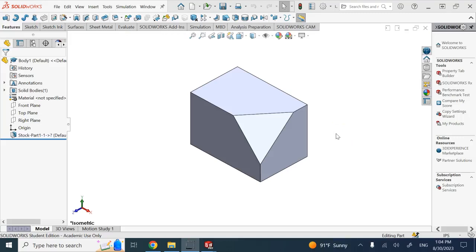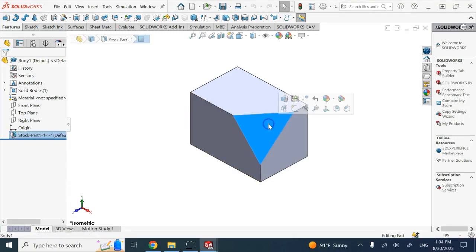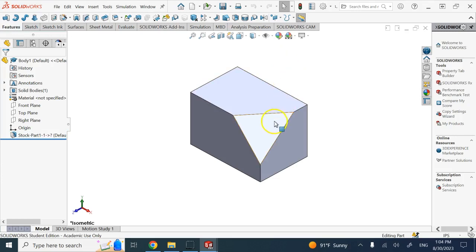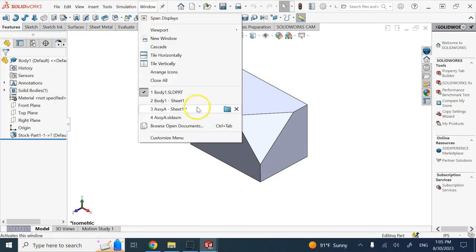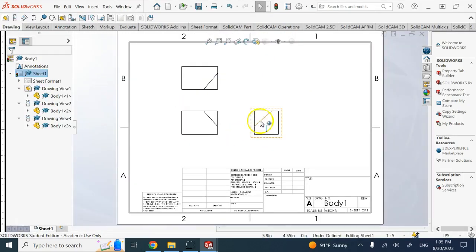Hello, everyone. One of the questions that you might have seen or came to your mind is, if I have what we call an oblique plane or plane type 3, the one that is not perpendicular and not parallel to any of the major three views, front, top, or right, and I want to see it in drafting, so basically do the front, top, and right view, then it would be something like this, right? In all three views, it is going to show as a plane.